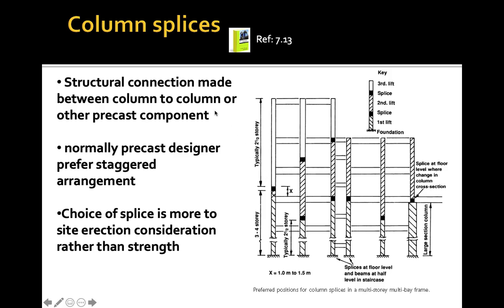This is for column splices, where we have structural connection made between column to column or other precast elements. Normally, precast designers prefer a staggered arrangement, with the choice of splice more to site erection consideration rather than strength.